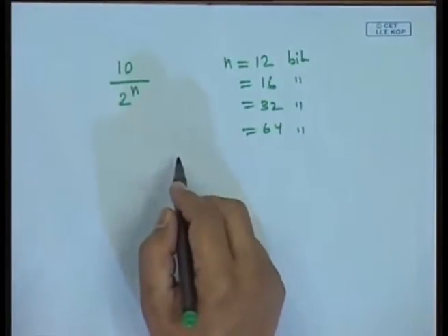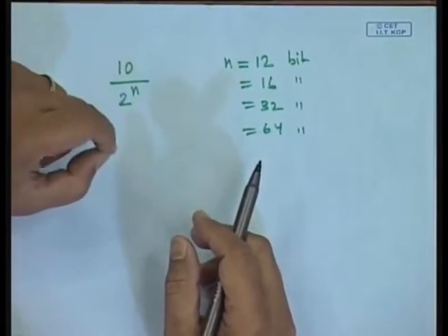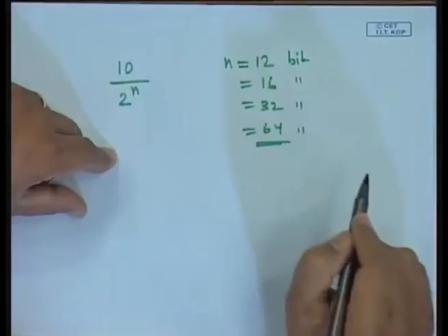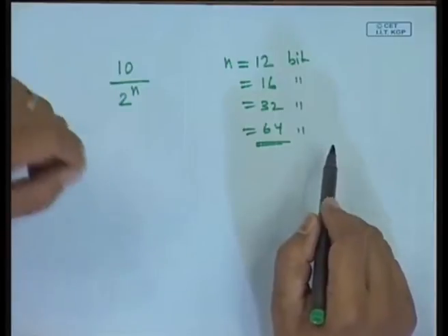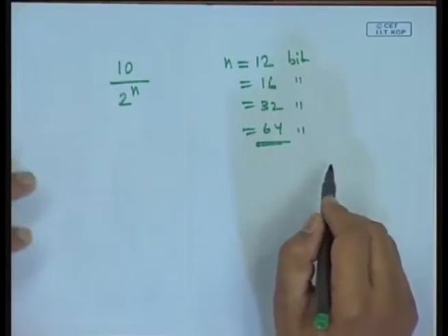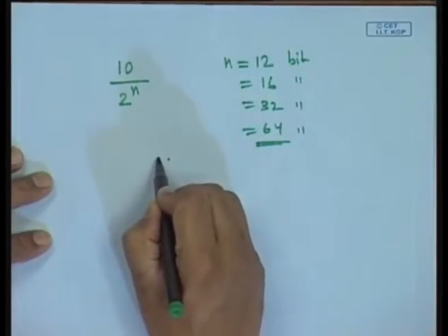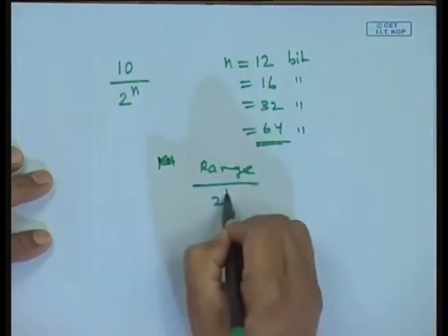a 3-bit or a 4-bit or a 16-bit machine. Because there are more levels: when you draw a graph, if you want to draw a crude graph, you have large boxes. If you want to draw a very fine graph, your divisions reduce, and then you can capture all these transients which are occurring. So, if we can increase the bit size, I can sense any small variations. And the least value the computer can sense depends on the maximum range divided by 2 to the power n.